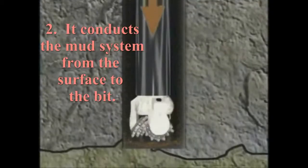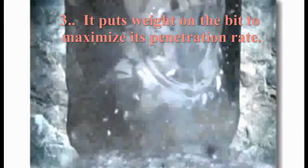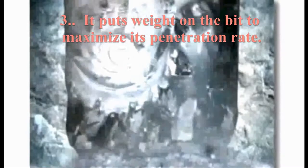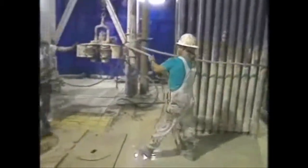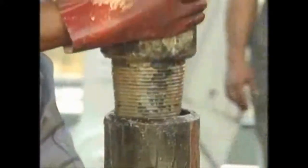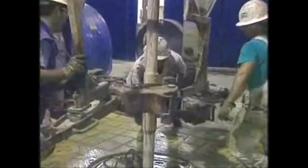Second, it conducts the mud system from the surface to the bit. And third, it puts weight on the bit to maximize its penetration rate. Made up of lengths of 30-foot stands of drill pipe with various diameters that can be screwed together, the drill string has 3 basic configurations.